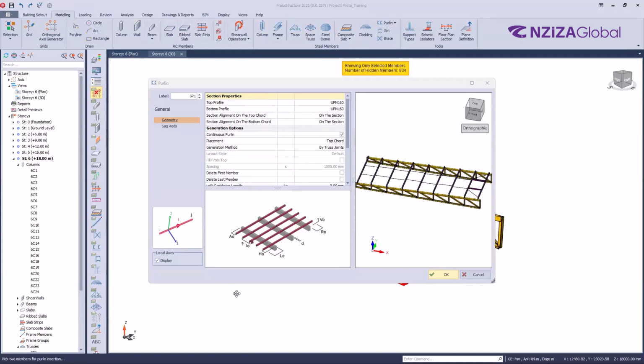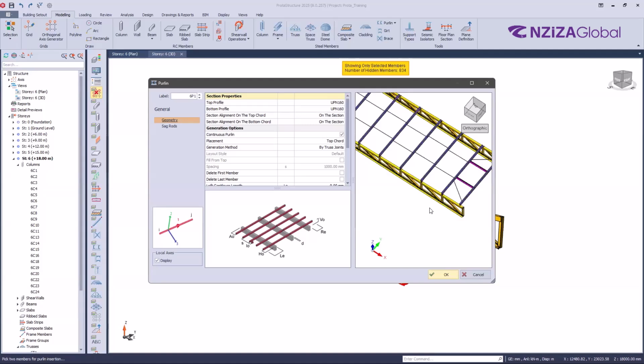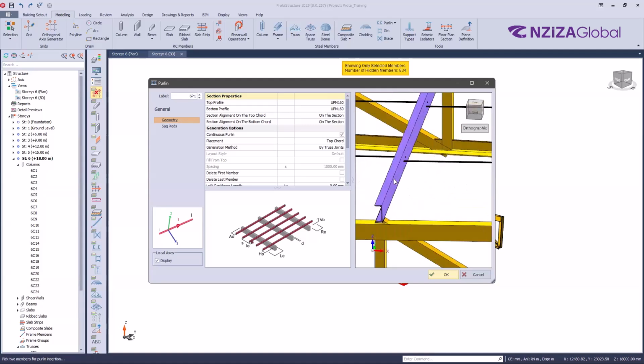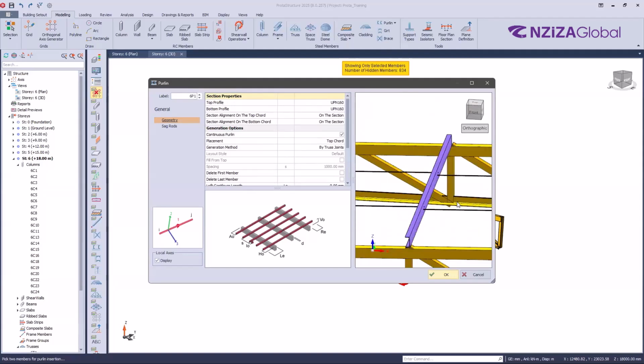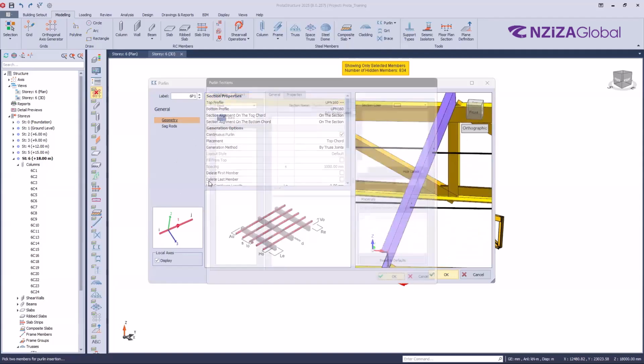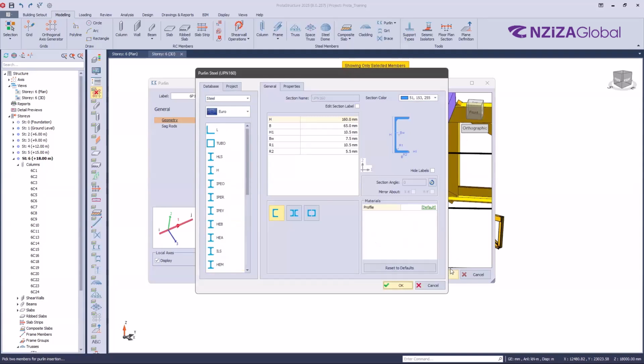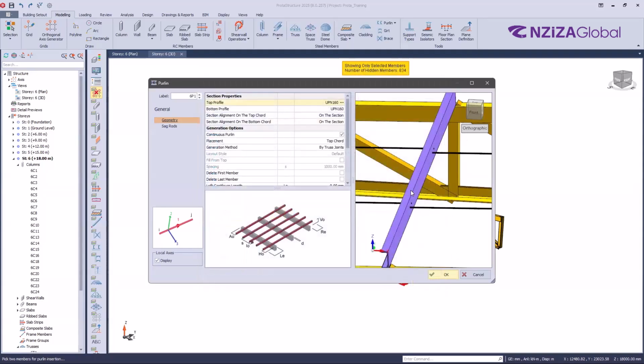We are back. So after reaching here, you can see how purlins have been placed. You can see the purlins here, these ones. Now again, you have different settings here. These settings are related to these purlins that we have created. These profiles, of course, will help us to change the section. Remember, if you click on one of these, you remember how we have changed the sections. So you can do the same for the purlins by creating this profile.